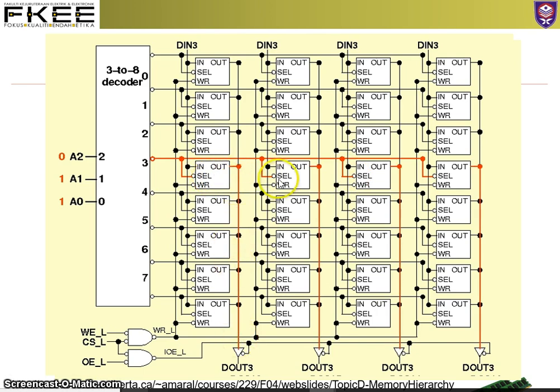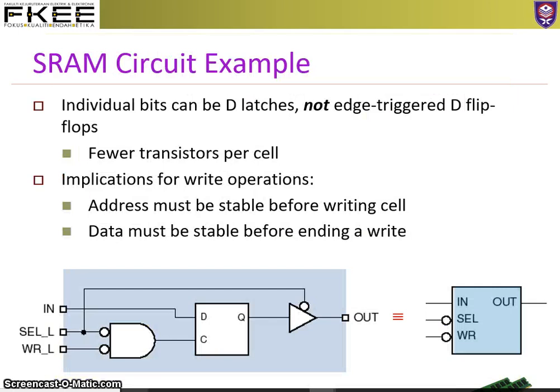It is connected to the output. But you have to control the buffer over here by using the control circuitry. So it will be output and chip select, so it will be turned on. We enable the output, so we have read the data from line 3.